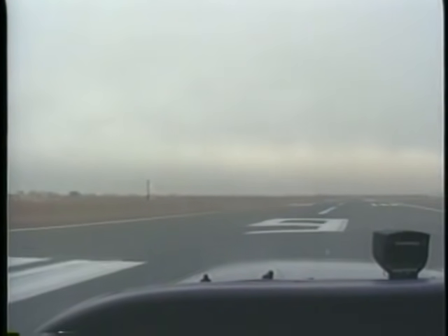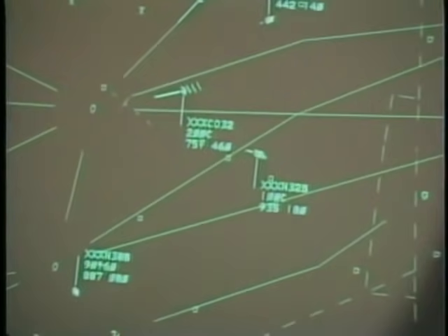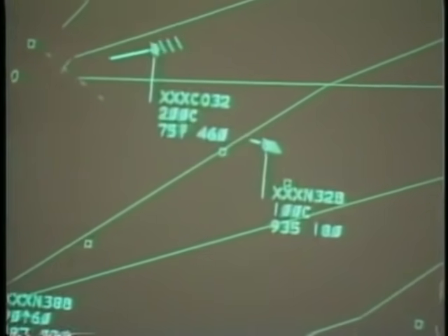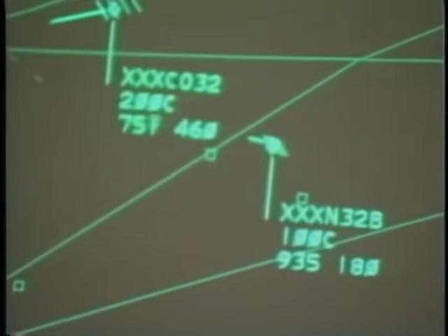In order to fly in controlled airspace when the weather is below VFR minimums, you must file an IFR flight plan and receive an ATC clearance. An ATC clearance is your authorization to proceed to your destination while maintaining the rules established for instrument flight. In order for ATC to provide the proper aircraft separation, you must not deviate from the clearance unless you are experiencing an emergency or receive an amended clearance.